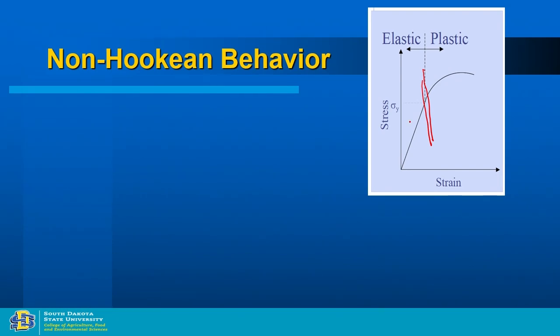They are not actual elasticity. So this is the elastic region. Even that is also an assumption only. You have to really do the test and find out under what strain level they will follow the same path. But we are assuming that this is elastic and this is plastic.